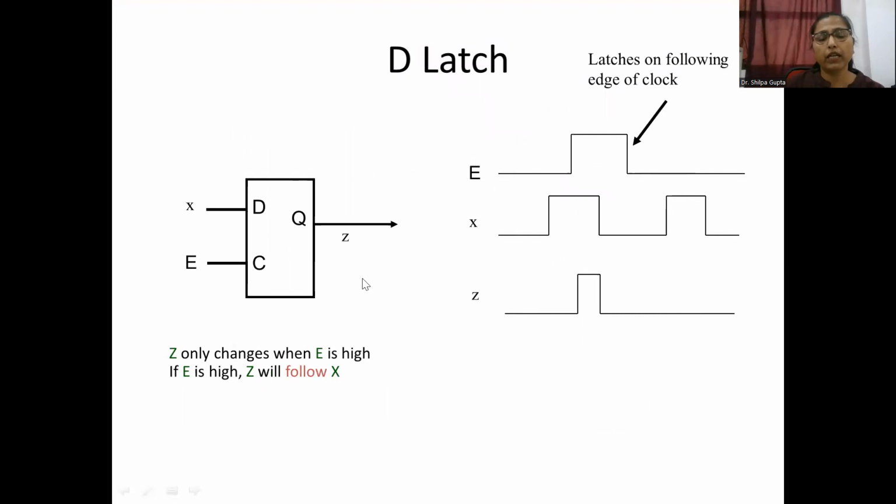Now this is the block diagram of the D flip-flop. Here the D input is applied. Whatever you are applying at the D input, the X's are don't care. Either it is 0 or 1, whatever you are applying to the D input. And then there is the enable signal, which is directly fed to the clock signal. Enable is to make this particular flip-flop active. Obviously, we are using the active signal as the clock signal only, so we will attach this enable signal to the clock. And this Q is representing the output. Whatever is applied is produced by this D latch. So this is the block diagram.